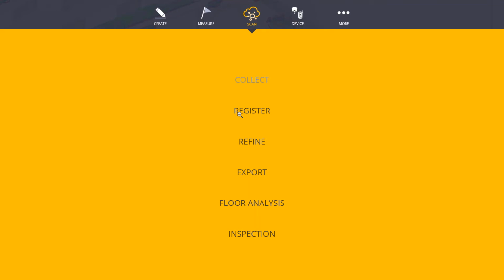Okay, thank you. One more popped in here. What's the best overlap distance to use as a baseline? That depends on what you're trying to scan once again. The way the registration process works nowadays, as I said, years past we had checkerboard targets and spheres. Now we use a plane-based registration.